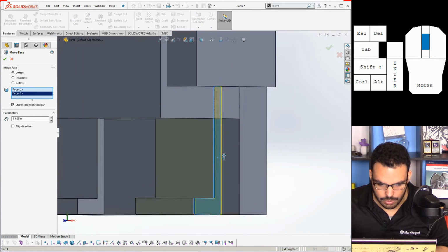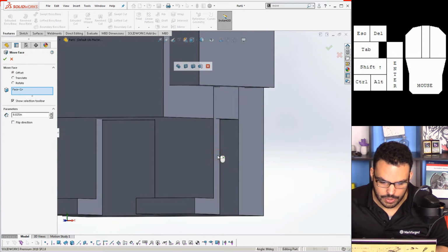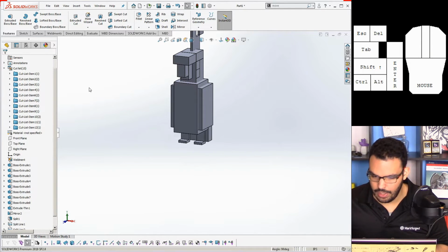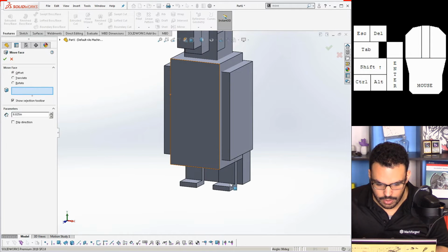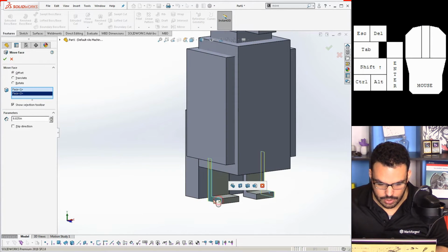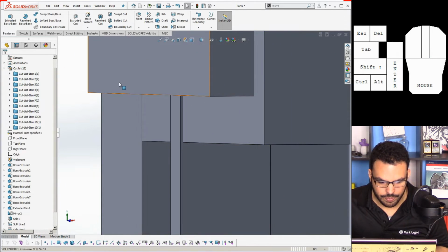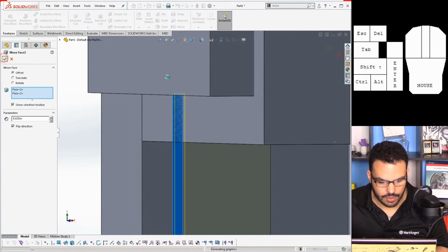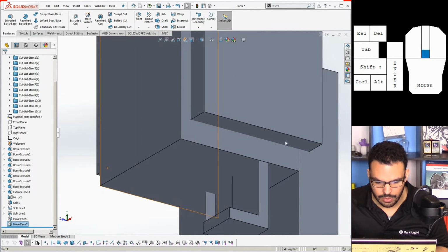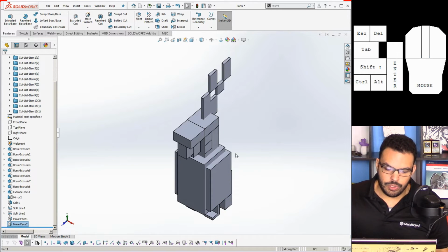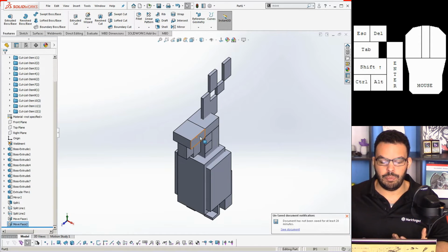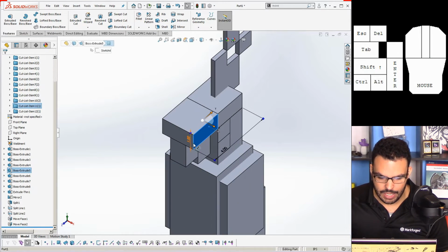I wonder if we can also do these ones. Well, the thing is, I don't want the foot sticking out. So I guess we'll just do it in 2 separate features. And I'll just go ahead and launch it again. Select these 2, and I'll say flip. The foot is set inward. Oops, no, that is incorrect. Let's go back. Flip. There we go. Now we have the foot set inward. Of course, I could have put that in the original size, but it's pretty cool because we can have this graphically appear correct, but the design intent is still there.